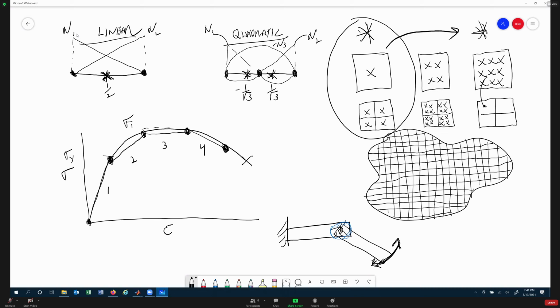At Siemens, I'm going to oversimplify it, Jacob, so I'm sorry, we go from Creo, which is Pro-E, so it's equivalent to something like SolidWorks, right into the ANSYS environment. You mesh it, you solve it, and you do all of your manipulation within the ANSYS environment. It's quite a complex process. That handshake is very tedious, and there's a lot of places where you can screw it up and get totally bogus results, based on either modeling decisions or errors that were made in Creo, or boundary condition decisions that you made in the software environment when you set up the ANSYS job.